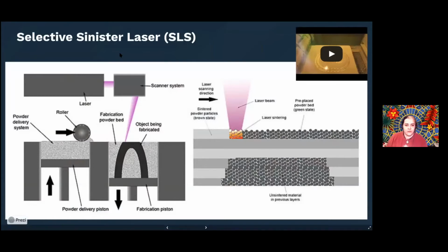And then last, we'll talk about this powder printer. Now this one that they have here is a little bit more of a commercial application. You have a piston in a basin that's full of this powder, and it has this laser that heats it. There's a thin layer of powder, and the laser sears it in a pattern, and then this roller will roll a layer of powder right over it, and then it'll sear that layer, and then it'll roll more, and then put a pattern, and so forth until you have your part. This one is showing maybe an aluminum powder.